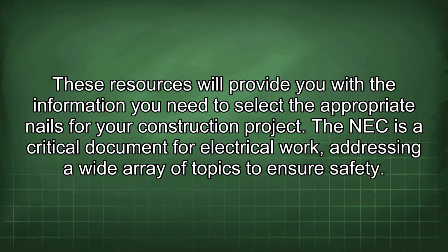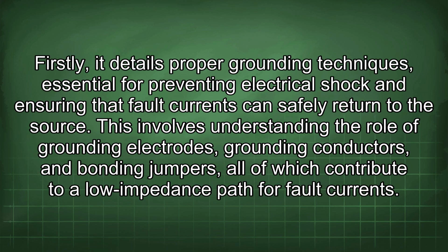The NEC is a critical document for electrical work, addressing a wide array of topics to ensure safety. Firstly, it details proper grounding techniques, essential for preventing electrical shock and ensuring that fault currents can safely return to the source. This involves understanding the role of grounding electrodes, grounding conductors, and bonding jumpers, all of which contribute to a low impedance path for fault currents.